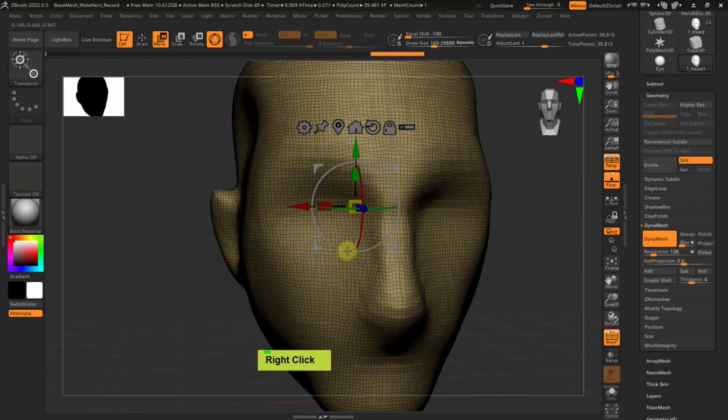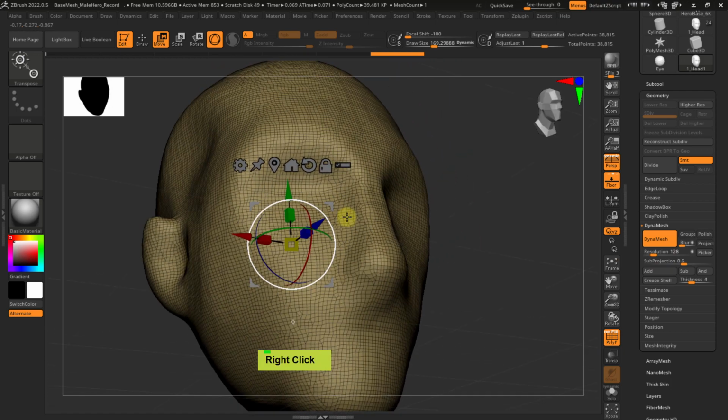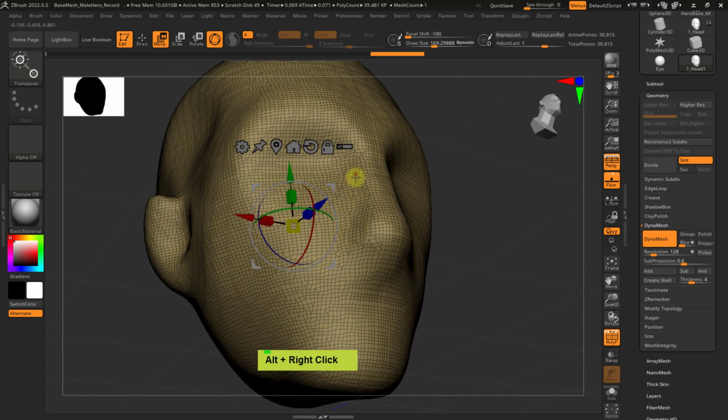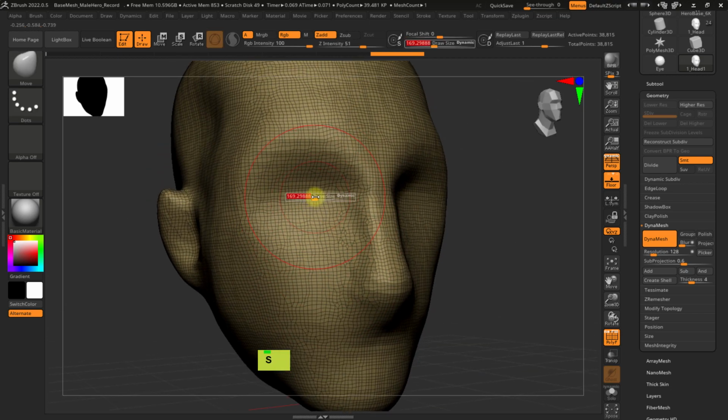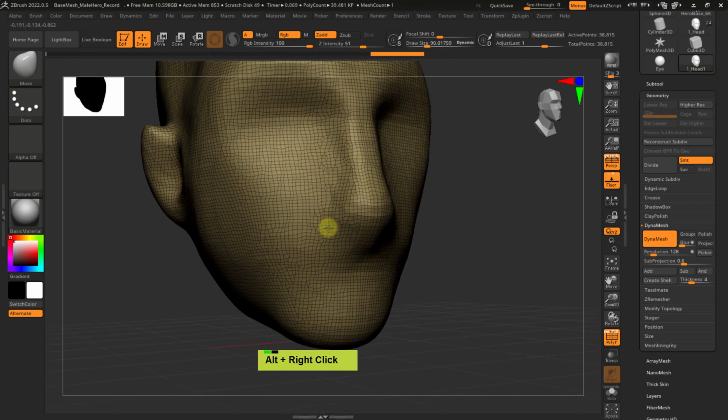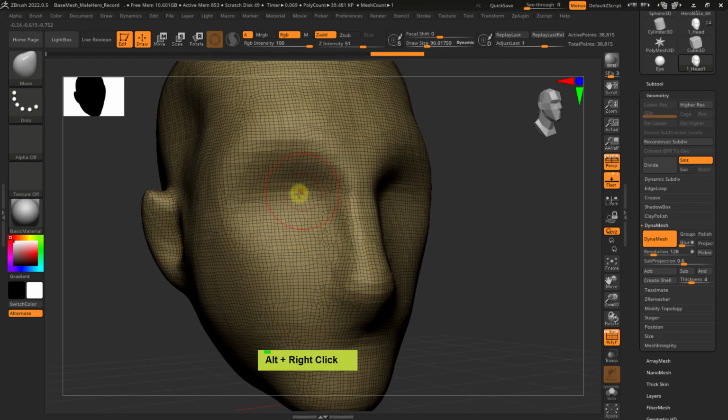So there's no eyeball. We will create the eyeball just in a second. But for now, my concern is just having a little bit more cavity for the eyes, and maybe the nose, maybe just sculpting some wrinkles here and there. So let me go with a BCB brush and using the Alt key, and of course I have to turn symmetry back on.